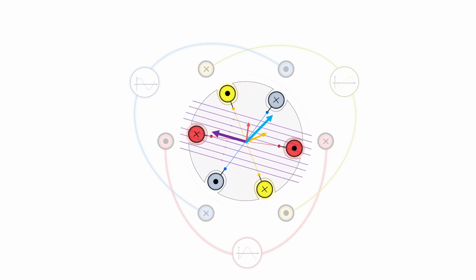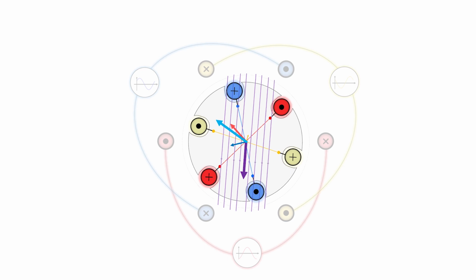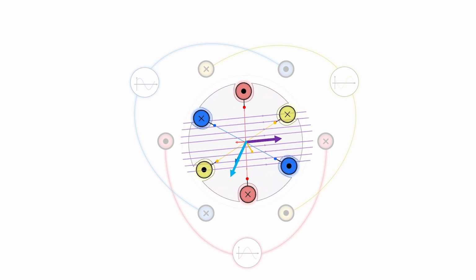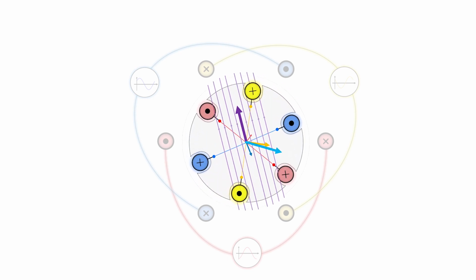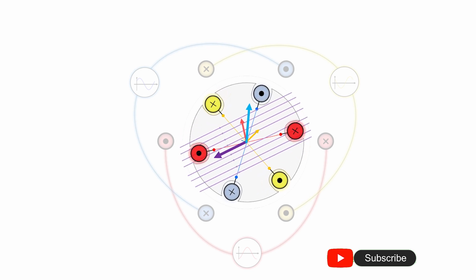Remarkable difference in induction motor is the way the rotor field is generated. There is no active source of magnetic field on rotor, no magnets, no supply. Just shorted rotor coils, as simple as it can get. The beauty of induction motor lies in this simple construction of the rotor.